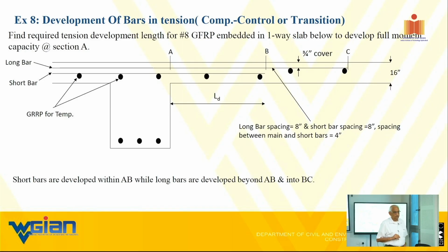That's not much, okay, qualified, that's not much when you wrap with glass fabrics. You could get that pretty high when you wrap with carbon fabrics. It depends on the carbon grade you are dealing with and so on. But yes, you can get about 10-15% increase in stiffness with glass, 30-40% with carbon.